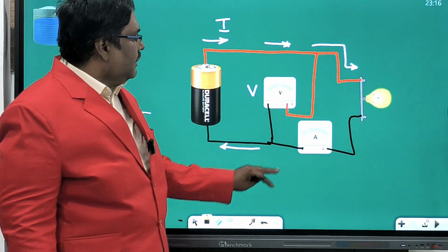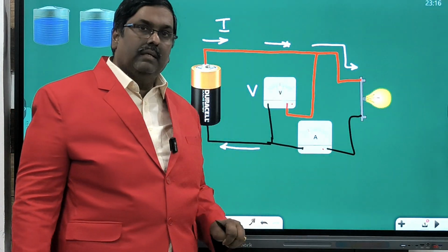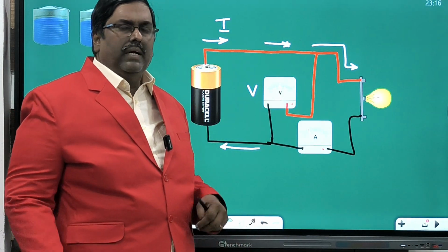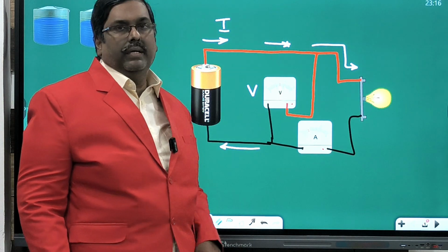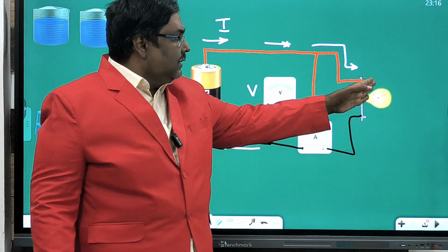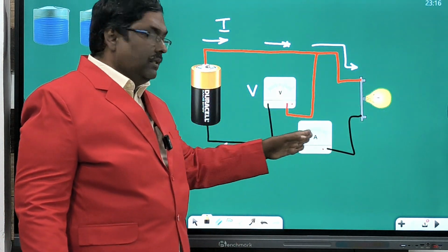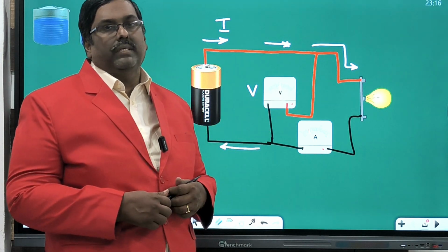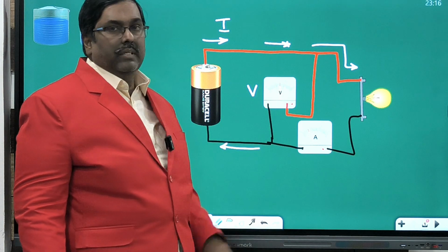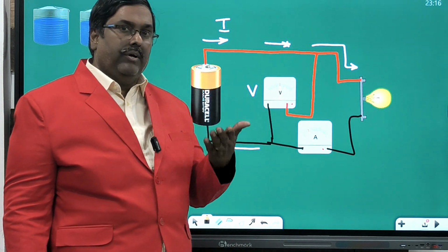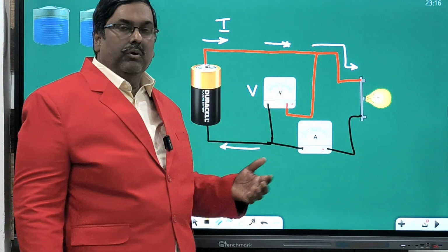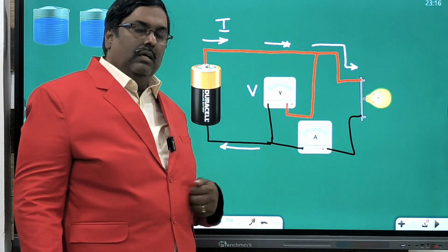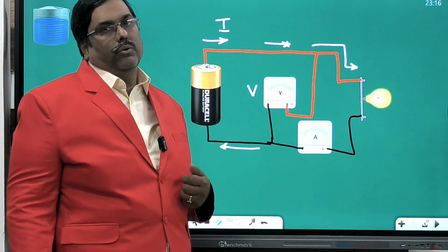Everybody is confused about where to connect the ammeter. But nowadays we are not using this ammeter, because all the current passes through the ammeter, so we would need a big ammeter for large motors. So we are not using this. We are using the tong tester. In future videos we will learn about the tong tester and how to use it.